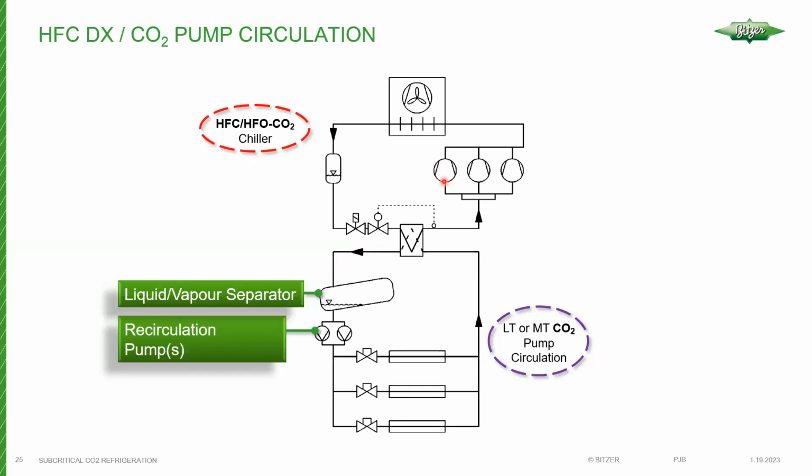So we have our compressors here discharging into a condenser, business as usual: desuperheat, condense, subcool, and then the liquid drains into a receiver where it can be transferred to one or more expansion valves on the system. And this could be a brazed plate type heat exchanger that just operates at a temperature, of course, that's lower than the CO2 loop. Basically, this is a wet type of system, where you've got CO2 being pumped through with some balancing valves, pumped through the evaporators, absorbing heat, and some vapor is formed.